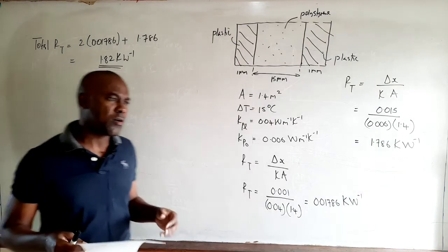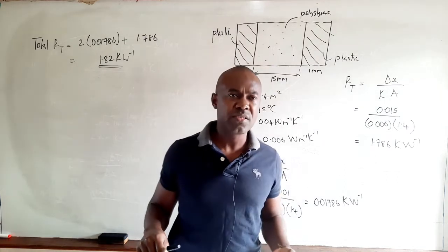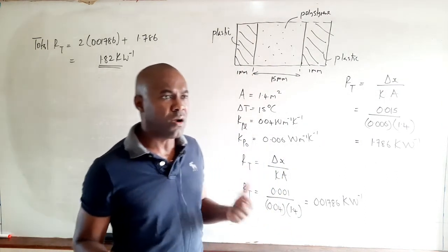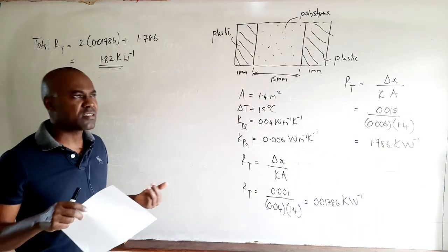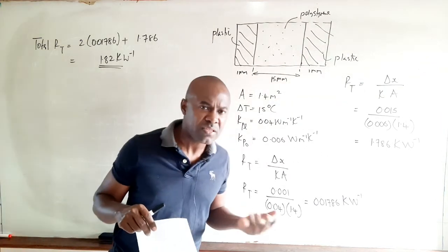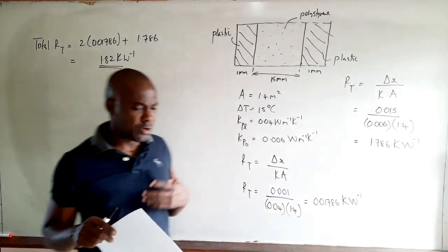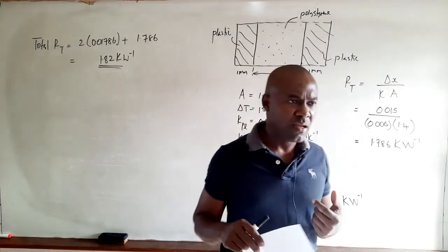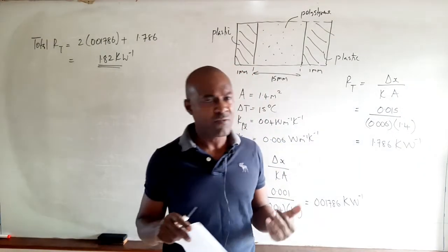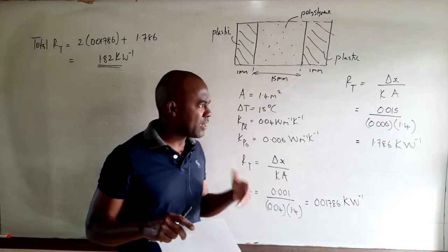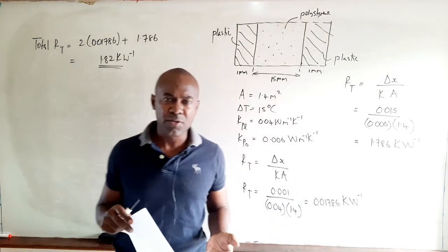Now basically, similar to how electrical resistance is a measure of the opposition to the flow of an electric current, we can say that thermal resistance is similarly a measure of the opposition to the flow of what we consider to be thermal current, right? So the greater the thermal resistance, the lower the rate at which heat will flow into or out of the material. Similar to electrical resistance, where the greater the resistance, the smaller the current that will flow along a particular path, the greater the thermal resistance of a composite material or a single material, the lower the rate of heat flow through it, right?